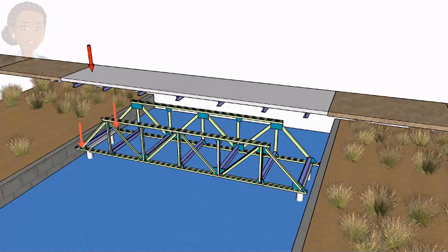When the truck moves forward, when it is somewhere between the first beam and the second beam, the load is distributed between the 2 beams in proportion to its distance from them. In turn, the beam loads are transferred to their respective end truss joints, like this. So, as the truck moves forward, this pattern of load transfer shifts forward from joint to joint until the vehicle leaves the bridge.